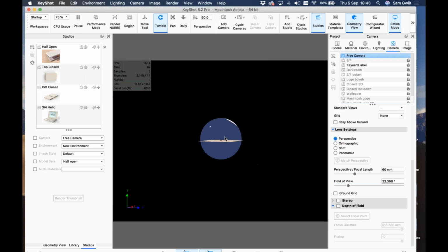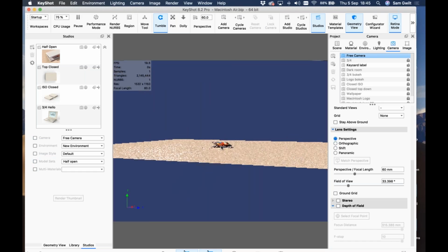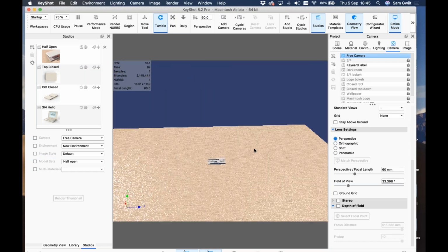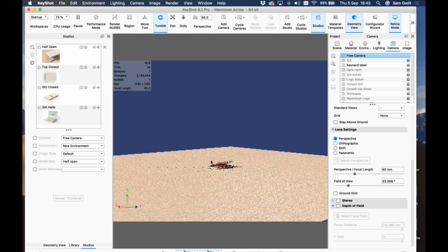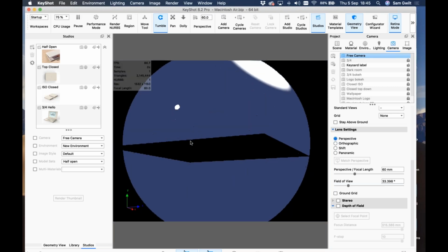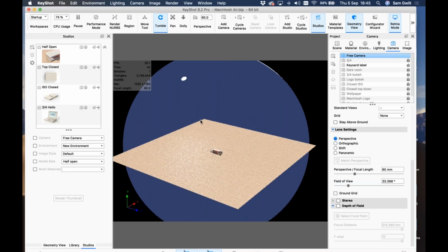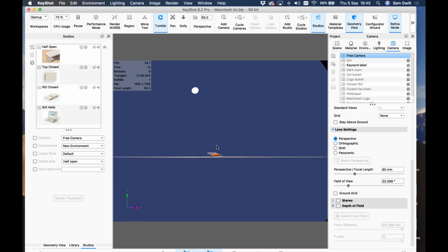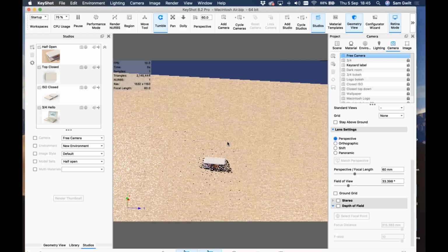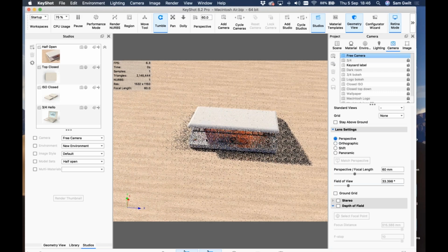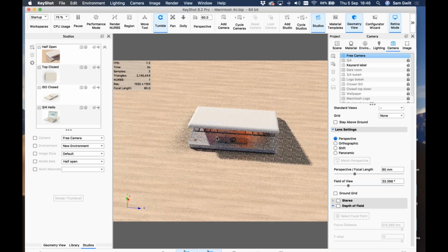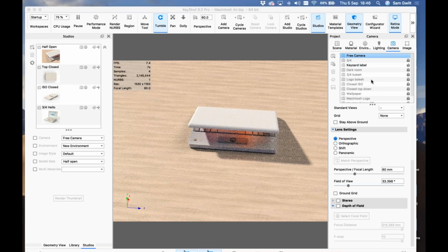All this is a blue background image because I wanted the shadows to have a blue tinge to them. And then just a couple of pin lights that we're going to, one, light the scene uniformly with this large one. Like I said, the larger the light, the softer the shadows are going to be. And then two, a really bright, small light, because that is what's going to give me the hard shadow that I really like the look of here. And by having a hard shadow, you can then really see the emissive light underneath. So that's there.